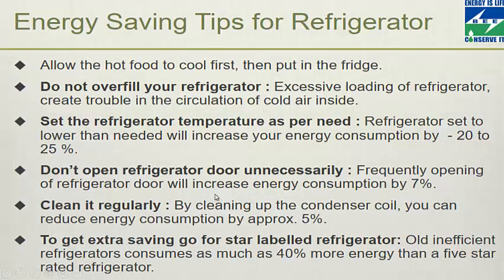Similarly, let us try to mention some saving tips for refrigerator. Allow the hot food to cool first, then put it in the fridge, because when you directly put hot food into the refrigerator, it may require more energy to cool it from that hotter temperature to the desired temperature.